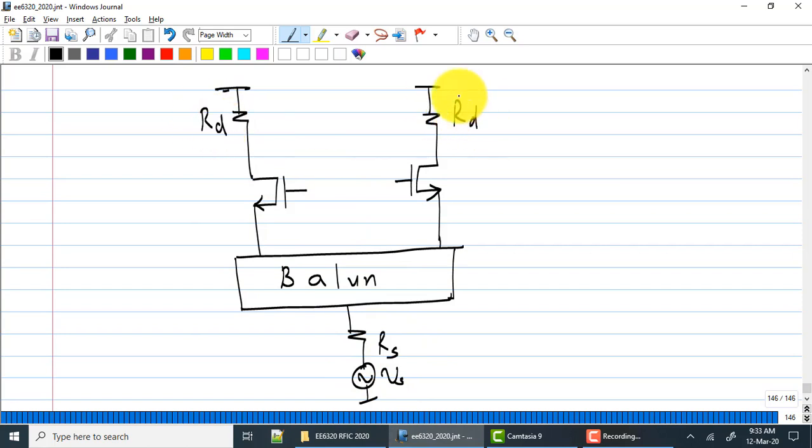I can have a differential amplifier taking the signals from the two sources, amplifying it, giving it to the gates. I could do that. The differential amplifier would add noise, its input capacitance would cause shifting and so on. Can you use a transformer here? Of course you can.